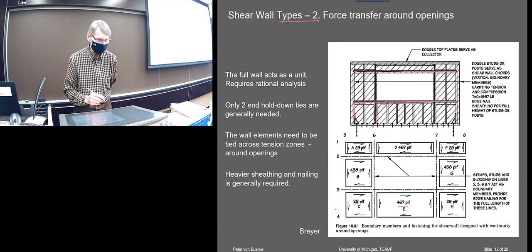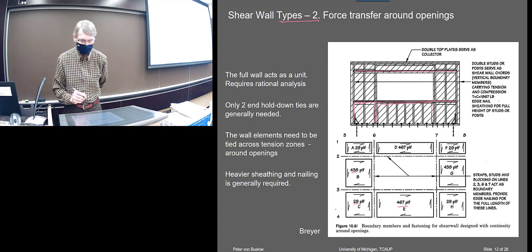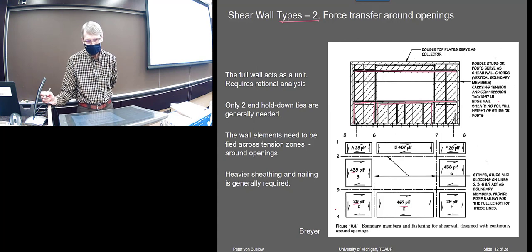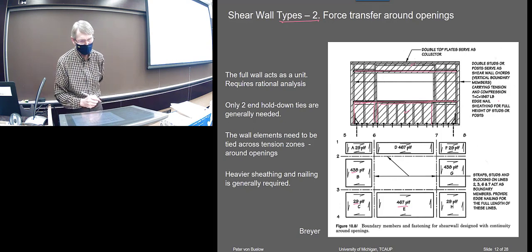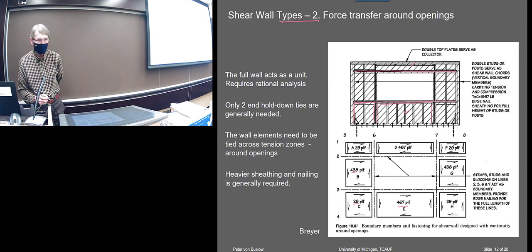So in terms of calculation, that's a lot more trouble. It ends up being a little bit stronger than the segmented, because you're picking up some additional strength from that middle part, but unless you really needed that strength, that probably would not be the best option.